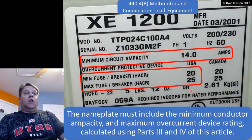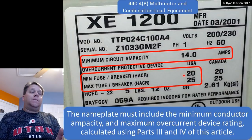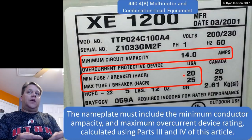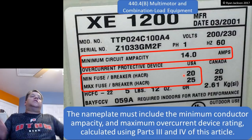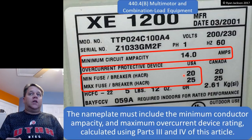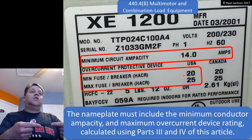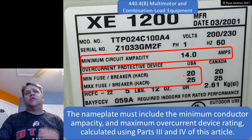Period. All right. By the way, we have to use at least a 20. If we don't use at least a 20, then the breaker will trip before the unit starts, and that's a code violation, right? Could we put this on a 10 amp breaker? No, because the motor won't start. If the motor starting trips the breaker or smokes the fuse, that's a code violation. We have to let the motor start. So there is a minimum.